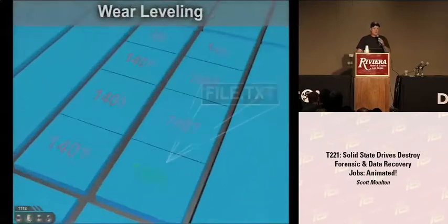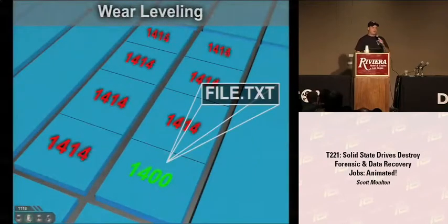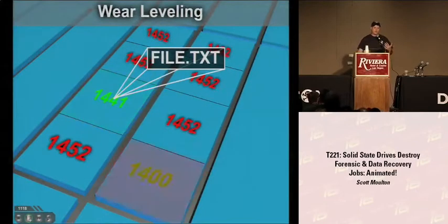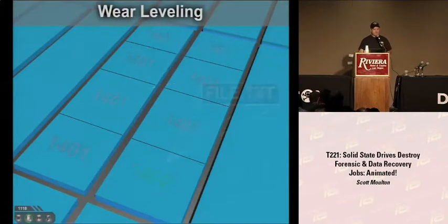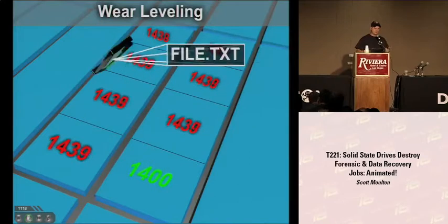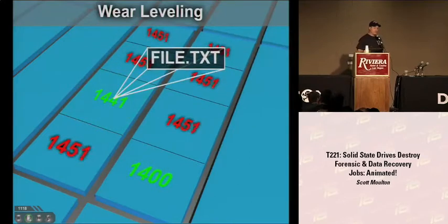Now, this is where I'm varying, and I'm not talking about physically what happens inside the NAND chips itself and what the manufacturer is buying. I'm now talking about where they're changing the source code and what the source code is physically doing on this chip to do something called wear leveling. Our problem is that over time, the cells will wear out and they will die. And there's some controversy as to how long that is going to be. But each cell will wear out and it will die sooner or later.